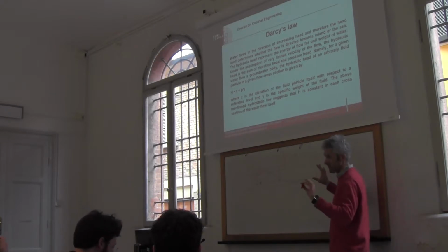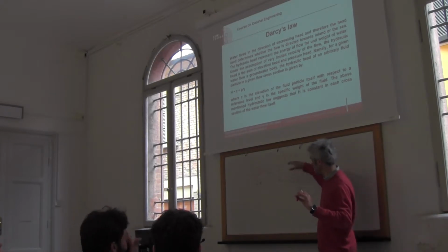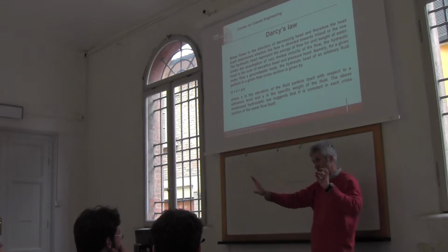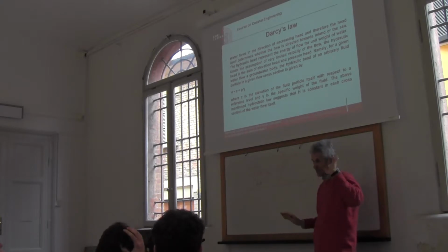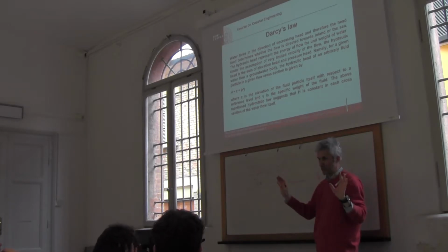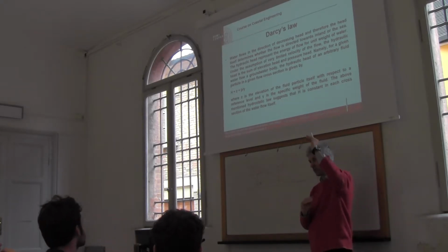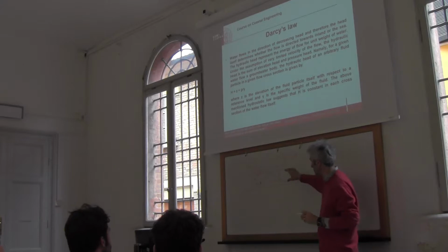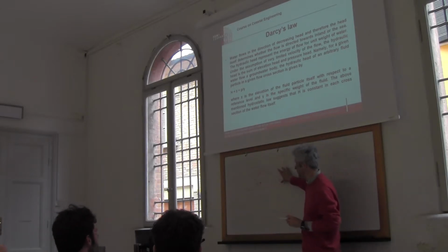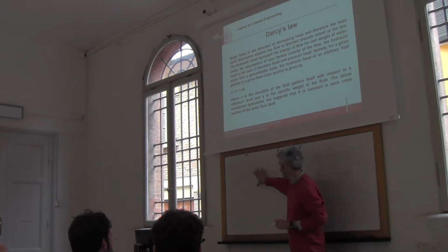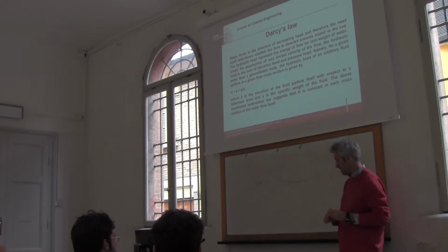And then I make confusion because here it's essential, if you want to make the sign consistent, to select the reference level in a proper way, but let's discuss that later, okay? Now let's focus on the absolute value of pressure, which is given by the weight of the water column above. And here I have two water columns pushing, one of salt water and one of fresh water, okay?